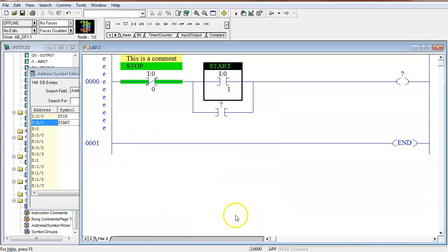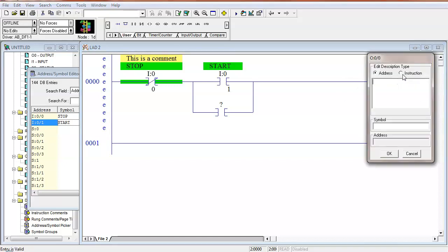So I'm going to call it start, because I want to call this one over here run. I'm going to assign this to output, colon 0/0. So this output on your trainer, right here, I've assigned to that. Wait, why is it 0/0?